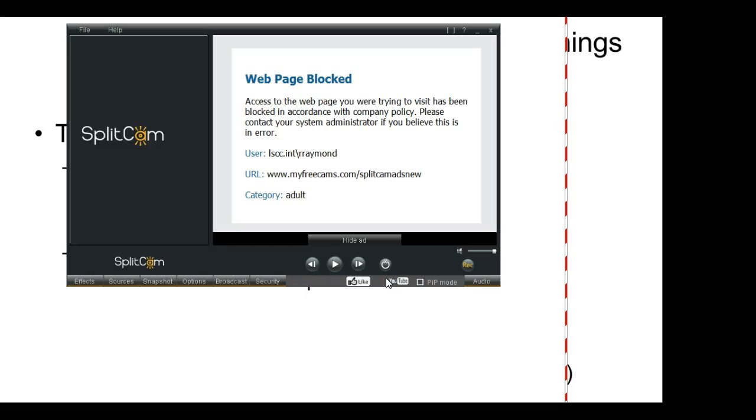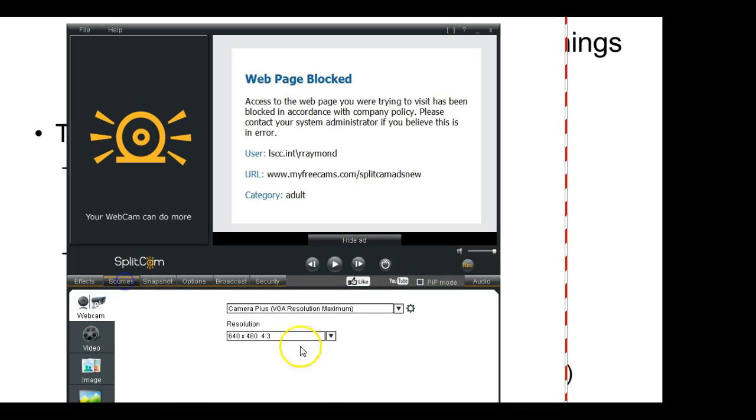So like a circuit breaker? Some circuit breakers use magnetics, and some circuit breakers use bimetallic strips. And some circuit breakers use a combination of both. Most home circuit breakers are basically a bimetallic strip, and you can see it if you ever pop one open.